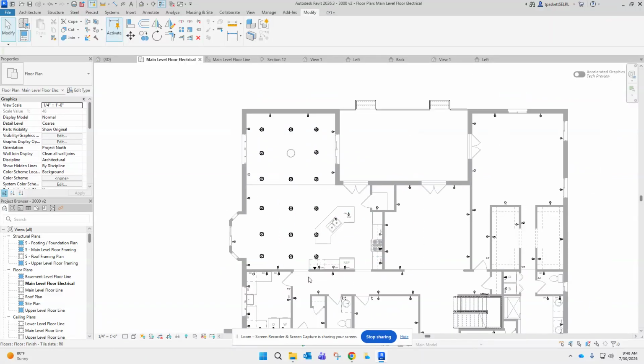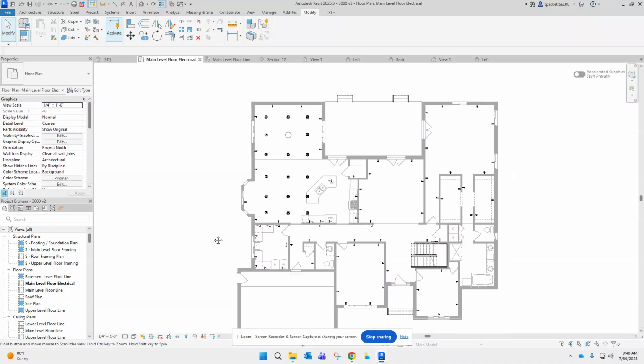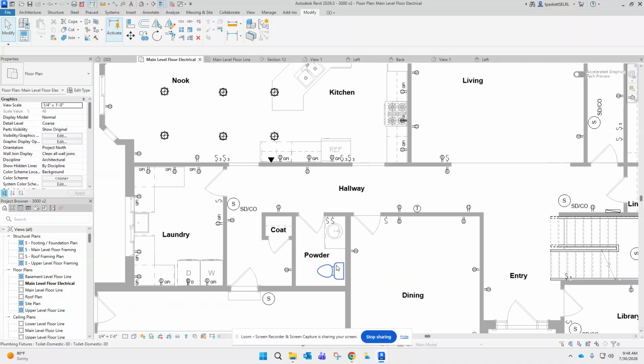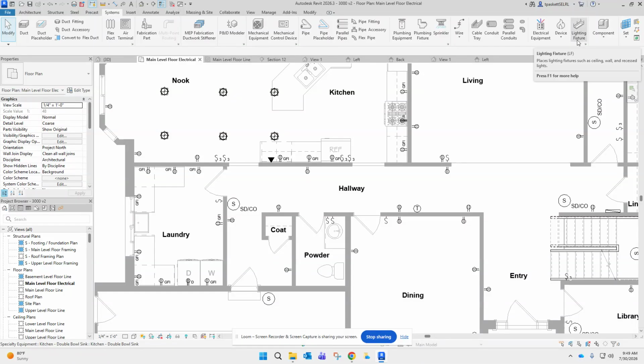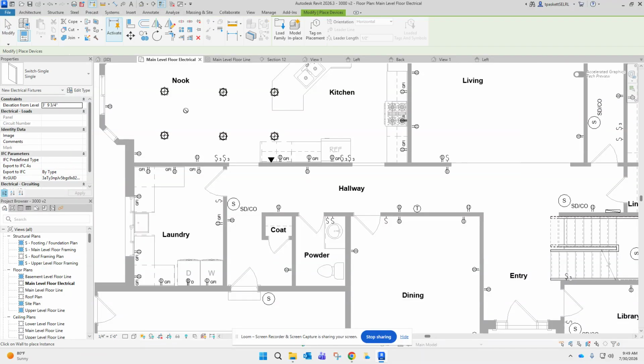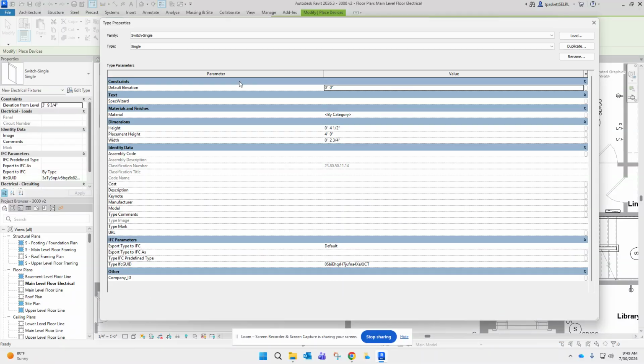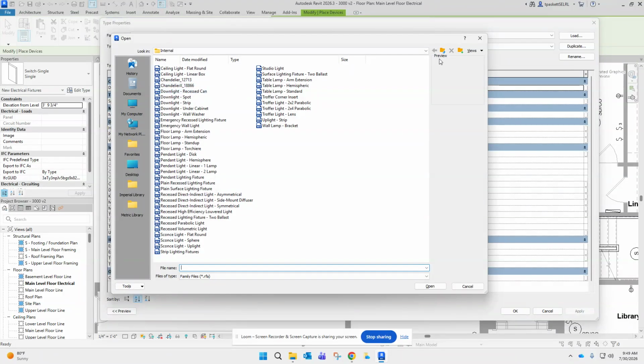Then let's go ahead and put that fan in the bathroom here. This room definitely needs one, and so I've got switches for that. So for the fan, we then go back into systems. We then go device. We then go down to, I think it is electrical system. And we'll go edit and load. Let's see if we can find that fan.